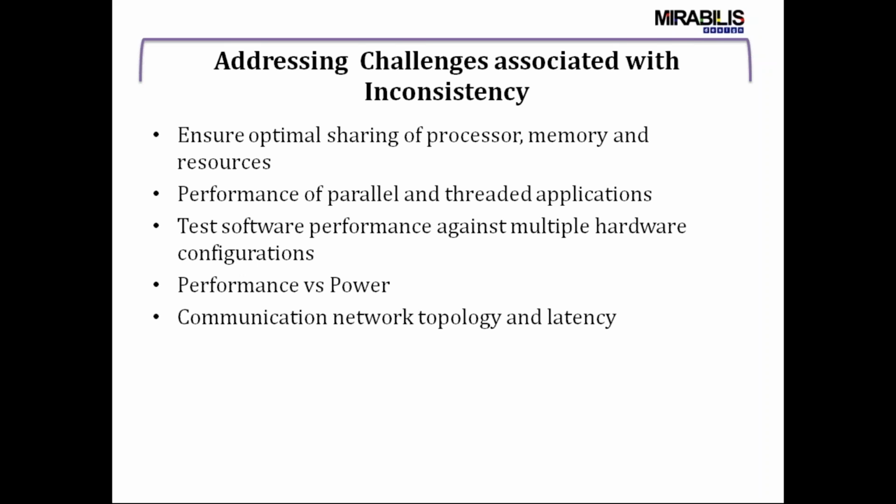And in addition to that, the kind of problems that you can address with Visual Sim is defining the communication network topology and making sure that the network latency is not exceeding your requirement or the kind of specifications that you might be having with you. So you can capture or define your network topology, which is connected with your processing resources or storage devices, and make sure that the end-to-end latency for a particular task from one node to another node is meeting your requirements as well.